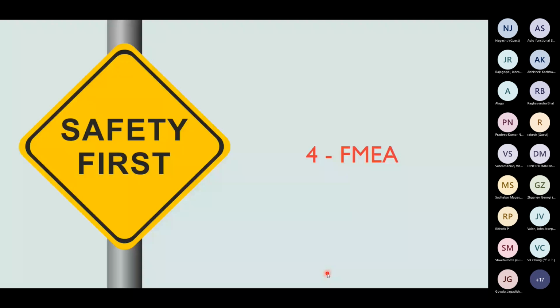We integrate multiple elements to form our system to meet the requirements. So we need to analyze those failure modes, whether they impact my safety-related functionality, and what measures I need to take to ensure those failure modes are addressed. Here we have two methodologies, and ISO 26262 recommends both FMEA and FTA. Based on the ASIL level, FMEA is a standard approach for all ASIL levels, and FTA is mainly recommended for ASIL C and D. It doesn't mean that we don't need to perform FTA. If needed, we can still use FTA as well.